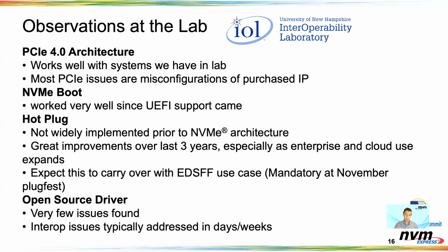It's worth mentioning, we do that hot plug only on U.2 form factor because, frankly, it doesn't apply. Hot plug doesn't really apply to an M.2 form factor or an AIC form factor. And we're expecting that, since the only thing changing is the connector from that transition from U.2 to E1.L or E1.S drives, we're really expecting that there'll be solid interoperability there as well. And this November, when we do our Plug Fest, November 2020, we'll be adding support for hot plug for EDSFF drives.